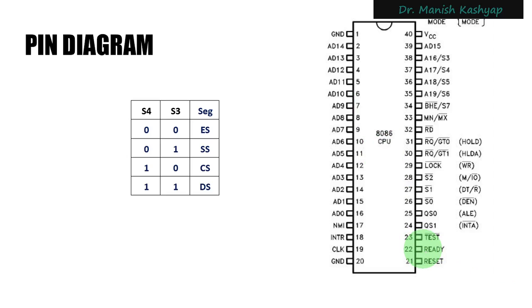So it will introduce more bus idle cycles. A read or write cycle has a specific number of T cycles, and here it will extend them, so that when the device is ready, it will be able to read the data. This is the usage of the READY pin.